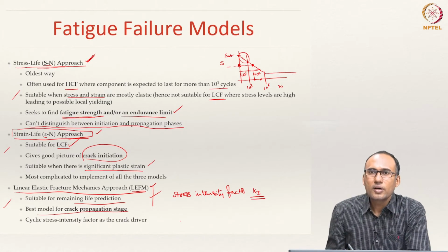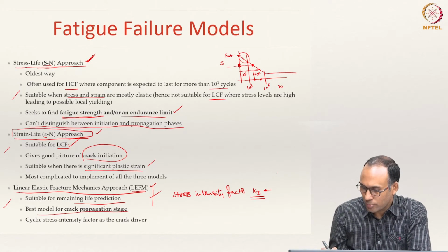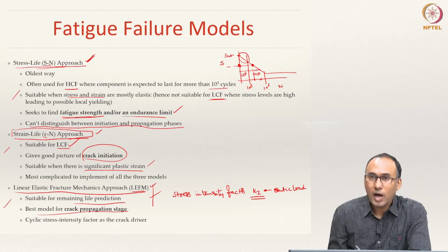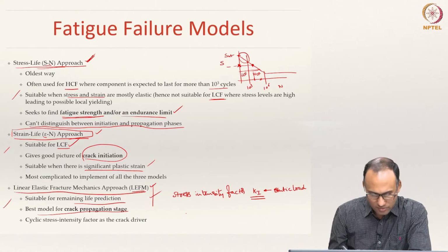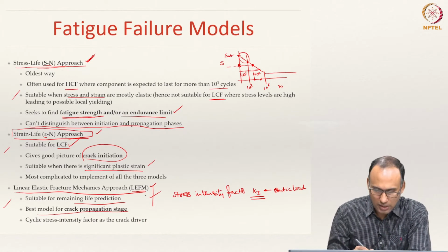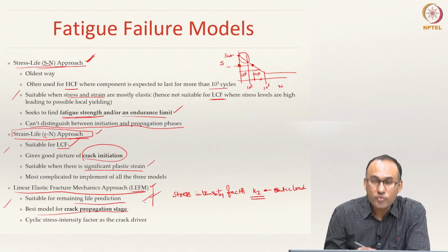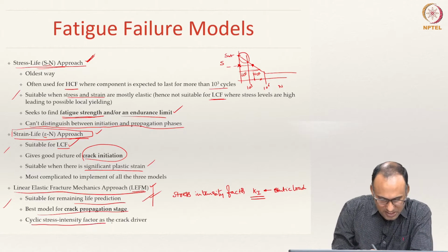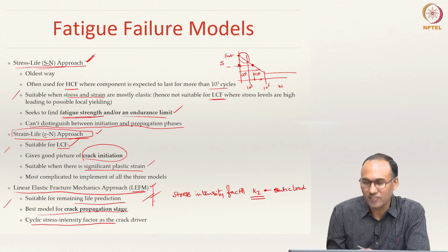But there we had a static loading. Now you have a cyclic loading, and hence when we apply the LEFM approach for crack propagation under dynamic loading, you have to deal with something called the cyclic stress intensity factor. That is the crack driver.